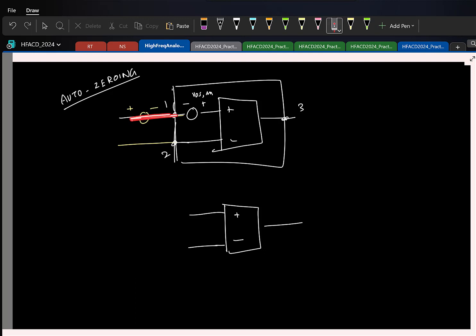Now, if you directly feed in the input, there is an offset. So you add an extra capacitor here charged to the appropriate offset voltage in the correct polarity so that it cancels. This is one way. There are a bunch of ways in which you can tackle offset actually. So in some op amp, I see there's a separate pin for offset. Yeah, that is there. So basically there what they will do is you have some programmable current source and they inject currents at appropriate nodes to cancel the mismatch, right? I mean, it depends on, that's what, there are different ways in which you can do it.